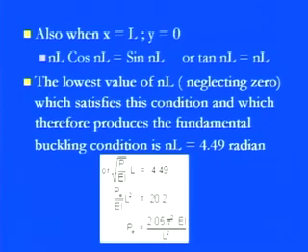We know that actually the length of the total cylinder part, you see the strut. So we have square root of P over EI into L is equal to 4.49, and then by squaring it out, we calculate the PE value, which is the fundamental Euler crippling load for this kind of situation where one end is fixed and one end is pin joint.